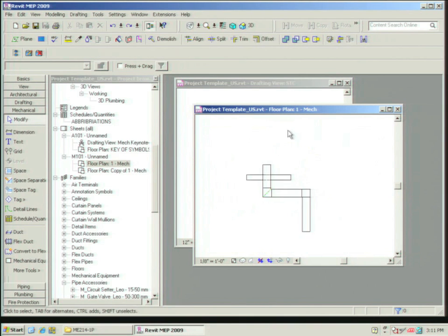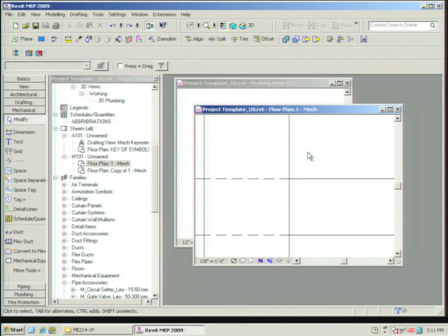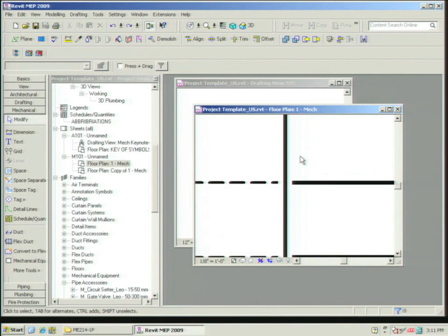Same as the gap size. I have this gap between. And in order to see the gap, it has to be thick line setting, which is right here. And that number can be varied by those settings, inside gap and outside gap setting.